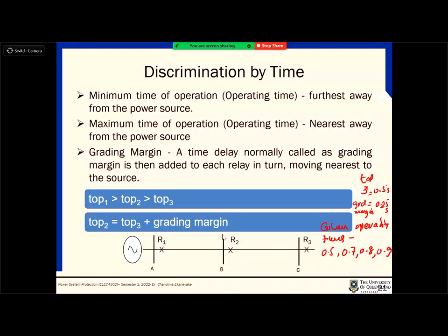If you are going above that, that is fine because then that keeps the coordination proper. But if it is less than 0.75, it may not, we don't know, right? One of the main things in designing protection systems is that you need to have security and reliability. So that's why you go for that. Okay.